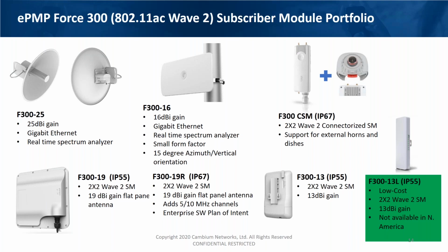I always say that if you can get a 5 megahertz channel and you're looking to deliver 20, 30 megabits per second, if you do that in a 5 megahertz channel, you're going to have the highest fade margin. It gives you another 3 to 6 dB of fade margin over using a 20 or 40 megahertz channel. So it's a really nice alternative if you're looking to really deliver super high reliability, 4 to 5 nines of availability. That's a great solution.